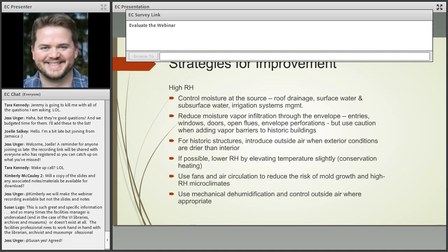I see this even in a lot of buildings that date from the 1970s in particular, where we didn't understand much about envelope design. We didn't understand much about vapor control, but we did want to positively pressurize. We wanted to bring outside air in and keep the unconditioned air out of the space. And a lot of those envelopes over time have failed, with positive pressure being one of the background causes.